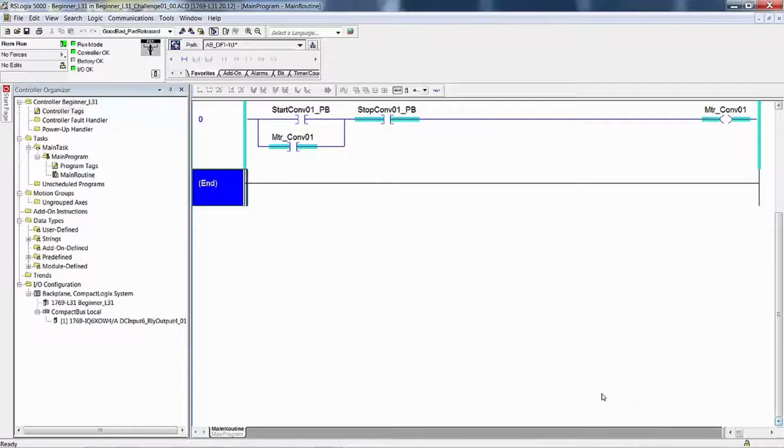Just in case you have forgotten, toggle bit flips the state once with each execution from off to on or from on to off, both of which you just did. 2 toggles equal the operator pressing and releasing the push button. The operator has now released the spring-loaded momentary push button, and the conveyor motor is energized and the belt is moving in a forward direction, transporting whatever or nothing that is riding on the belt.